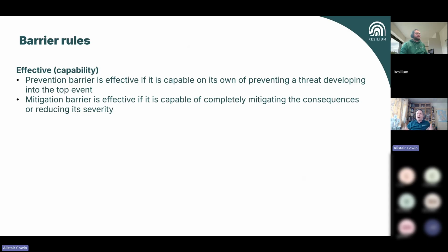That's the barrier, is that we have a detection system, annunciation, and we leave. If I don't leave the building, I potentially die in the building in the smoke or the fire. So when we describe our barrier, we should really be describing the effect, or at least the system that is providing that, and it must be capable on its own of preventing the threat developing.